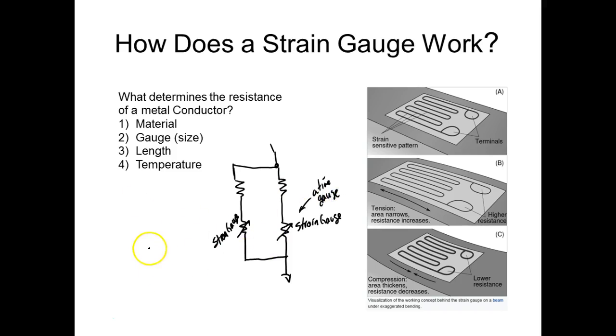So these things will be wired on the same chunk of metal, and they're right there together. So this is the metal that's measuring. One strain gauge would be mounted like this. So this would be what they refer to as the active gauge. And the other strain gauge would be mounted like this.